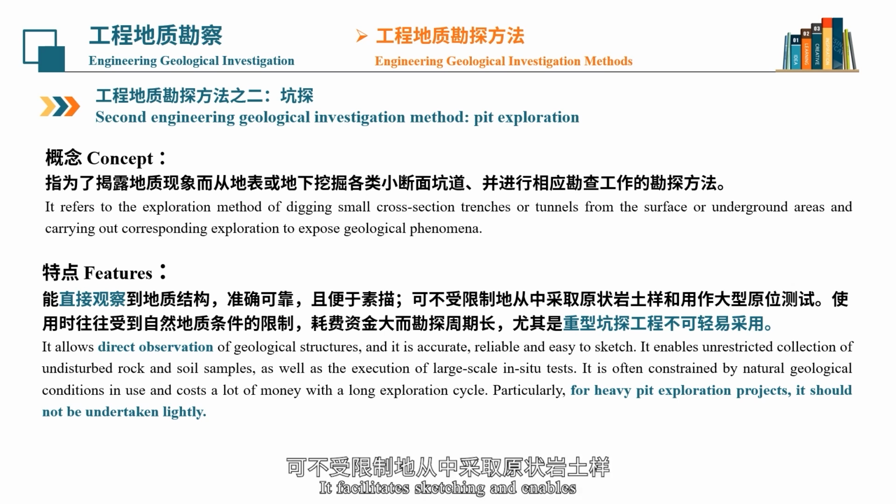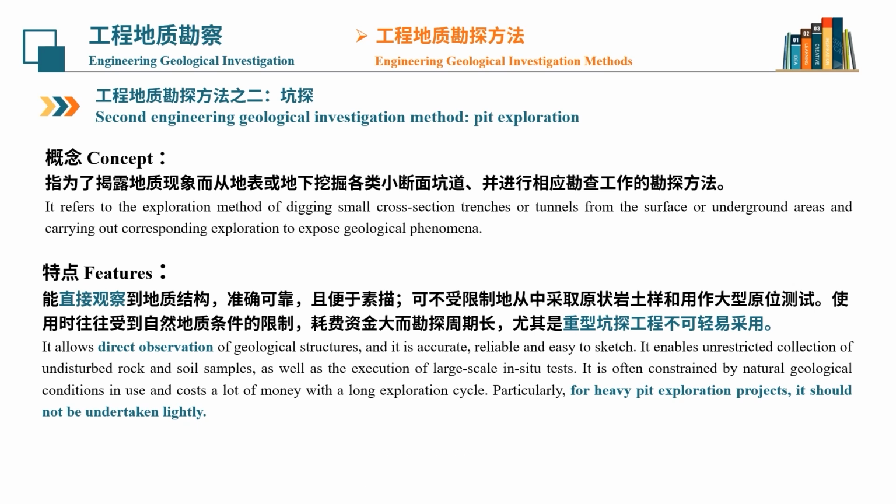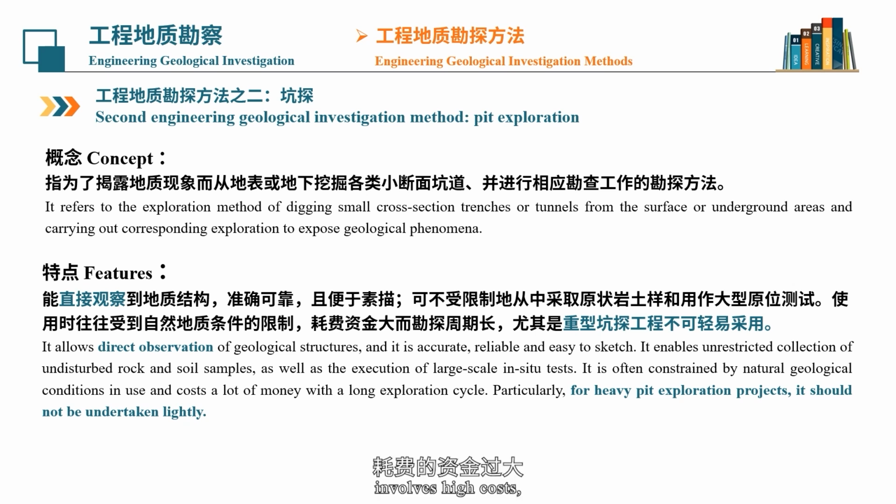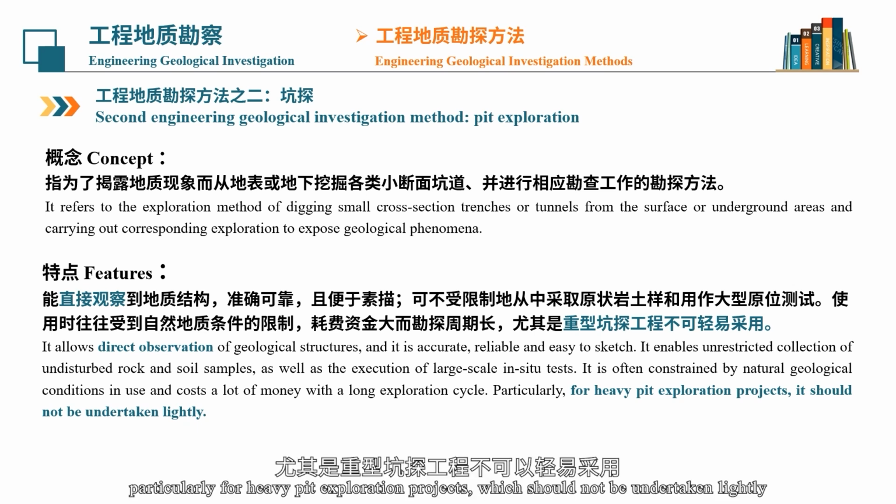It facilitates sketching and enables unrestricted collection of undisturbed rock and soil samples, as well as the execution of large-scale in-situ tests. The use of test pitting is often constrained by natural geological conditions, involves high costs, and requires lengthy exploration cycles, particularly for heavy pit exploration projects, which should not be undertaken lightly.